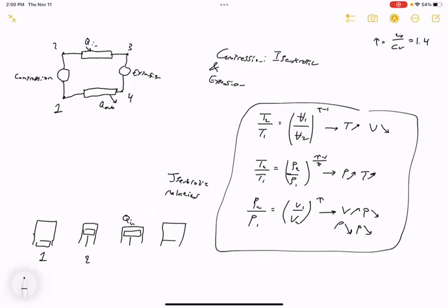And then we expand back down, and this is where you get the work output. You throw the piston from very high up to very low down. That work is what you're getting when you run an engine of any kind. And of course, to go back from state 4 to state 1 is when we have that heat rejection. But the point is that this heat is added, and the same way it's rejected, at constant volume, right? The piston is not moving when the heat is being added or rejected. So necessarily the volume is constant. So it's an isochoric process. The volume is constant, the specific volume is constant.